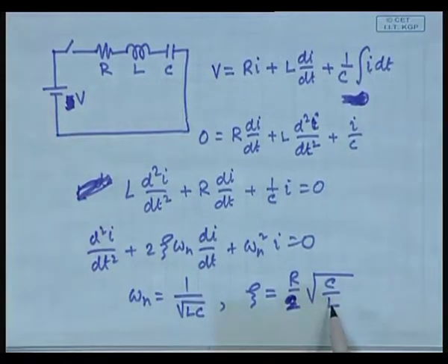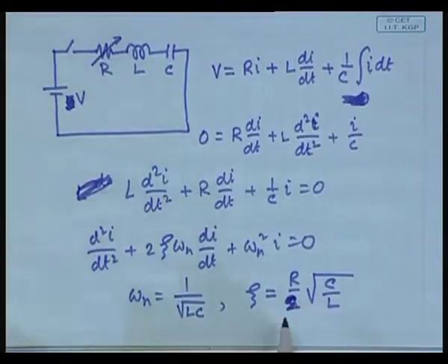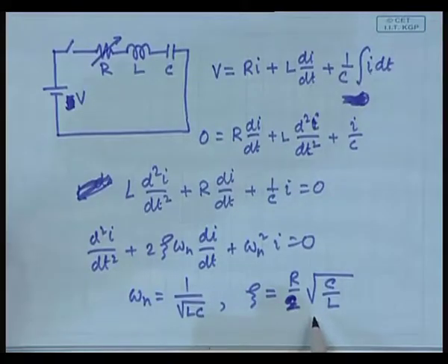Okay. So, if you have these parameters and say you have this as a rheostat, and if you smoothly increase it from a small value to a large value, then what will you see? Initially it will be underdamped, it will be an oscillatory solution, because the eigenvalues will be complex conjugate, and as you change it, it will slowly become firstly a critically damped situation when this is equal to exactly 1, and then it will become overdamped, fine.